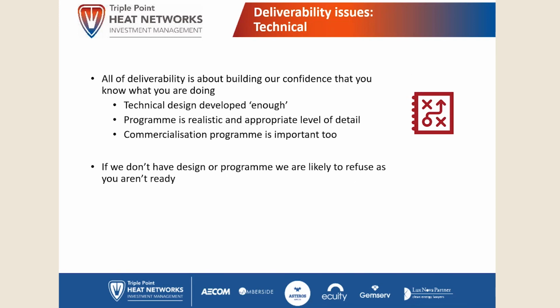Technically, again, as it says, it's about confidence. The level of design varies greatly with the approach you have to tendering. So what are you tendering? Are you tendering a concession? Are you tendering a D&B contract? Are you tendering a traditional build contract with a very detailed design during commercialization phase?